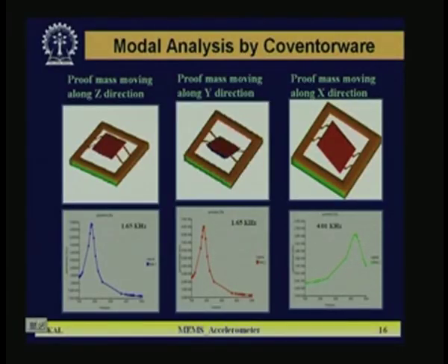If you plot the modal frequency versus response, at the resonance frequency the maximum output will be obtained, but we don't want to resonate the complete structure, as that may create problems for the total device. We know our devices are all DC and very low frequency signals are there in those sensors, so if we do the mechanical analysis of the complete structure, for different modes we have to see whether the frequency is above 100 hertz.